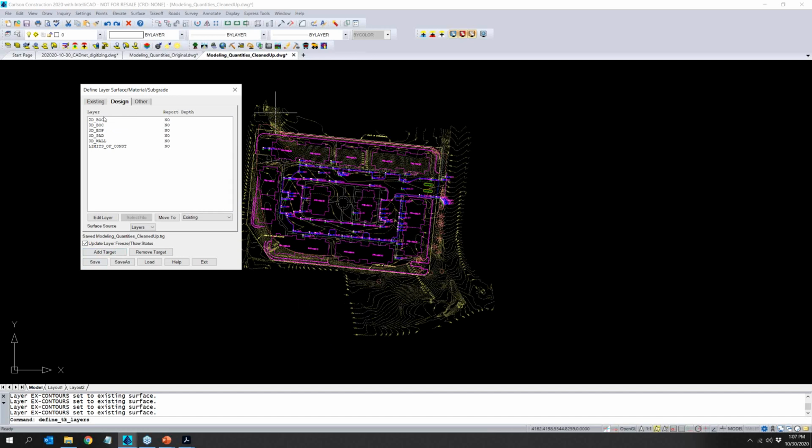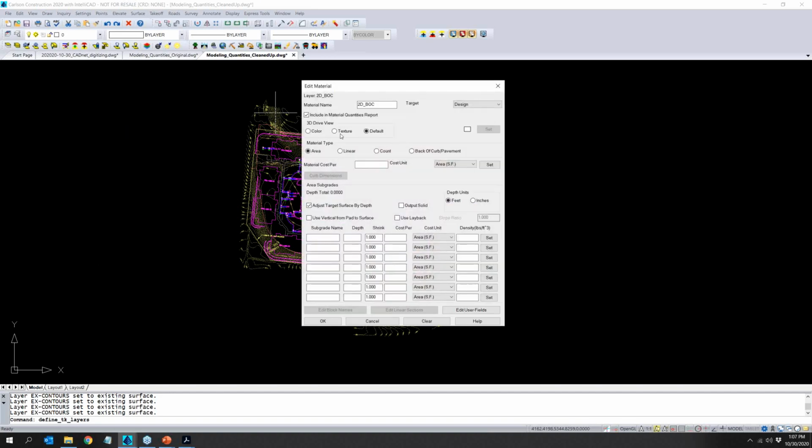Now, my design, I said this has a 0 elevation. For the most part, it was really just used with my spot elevations to elevate to this layer. But I'm going to let this do double duty, and I'm going to have it measure 24-inch curb, and I'll do a linear unit length.